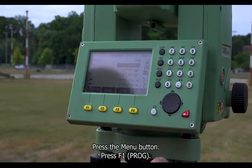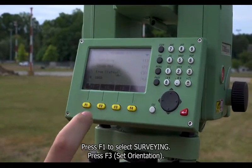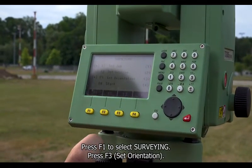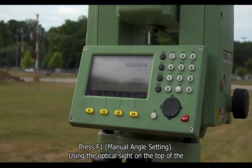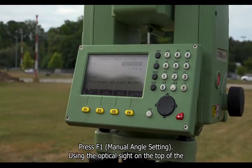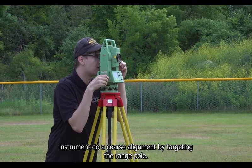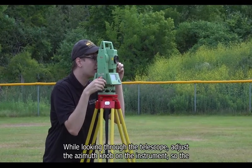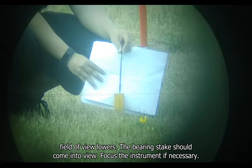Press the menu button. Press F1 for Program, press F1 to select Surveying, press F3 to set the orientation, and press F1 for Manual Angle Setting. Using the optical sight on the top of the instrument, do a course alignment by targeting the range pole. While looking through the telescope, adjust the azimuth knob on the instrument so the field of view lowers. The bearing stake should come into view. Focus the instrument if necessary.